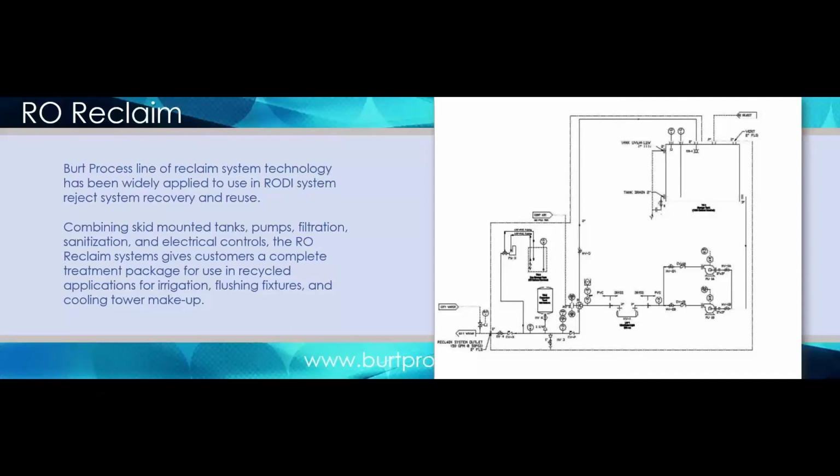One of the things that came up recently, just as a little bit of a side topic here, is what's referred to as RO, or just high purity water reclaim. Just want to touch on it here for a second. Obviously, with any RO, you do have a reject stream which is involved in it, and on a very small system, say 3 or 5 GPM, your reject could be 1 or 2 gallons. You start talking about very large systems, say 50, 100 GPM, and you could have 25 or 30 gallons per minute when the RO is in operation of just basically rejected city water in those cases. So there has been a push recently to implement RO